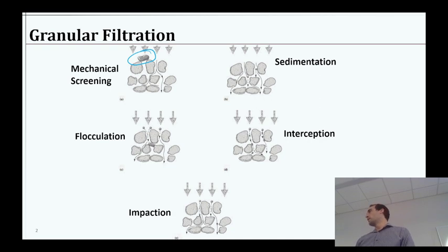If that was the only way to filter them, all the pores would get clogged, and then we'd just get no flow through it, and it would be a problem, right? So sometimes that'll happen. There's going to be a few particles that just can't make it through. Somehow they're in the water and they'll get rejected. But most of the time, what we're going to have is something like either particles flocculating together.